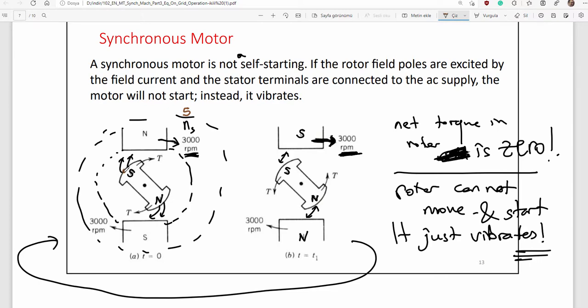Now, here's an observer. Assume that. Please tell the story. What you see right now. And an observer sitting on this pole says that there is a magnetic rotation around me, but it is very slow right now. So when you apply excitation to the rotor coils, DC field current, then there is a sudden locking. We lock or synchronize those two magnetic fields at a lower frequency.